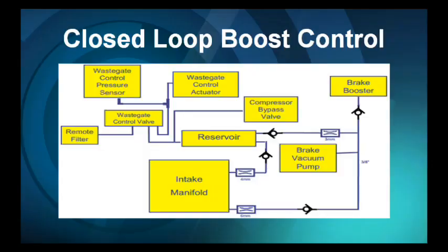Most systems will bleed off that pressure, which will change the gate and increase the velocity of exhaust flow to the turbine, thus increasing the turbine speed and the turbo boost pressure. That bleed of pressure between manifold pressure and the wastegate canister is controlled by a wastegate control solenoid. It is a low side ground controlled duty cycle to that solenoid.